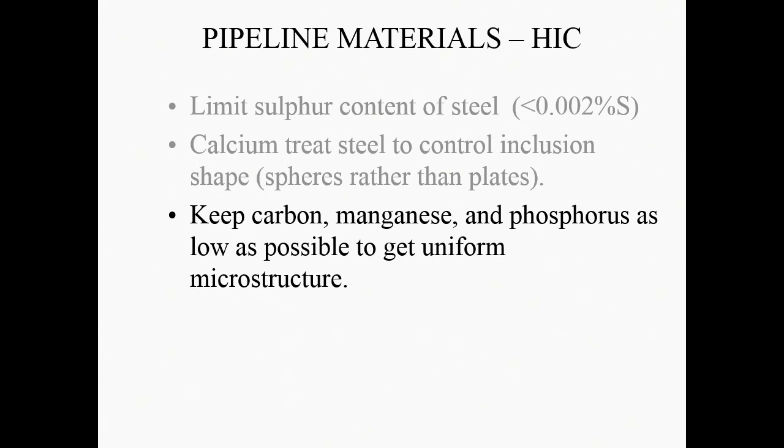It doesn't affect the hardenability, but it's another embrittling element that you want to reduce, like sulfur. Not quite as bad as sulfur, and a small quantity of phosphorus is good because it will increase the strength of the steel, but too much phosphorus and then you can get brittleness, so you want to avoid that. And hydrogen just makes all these things worse. So anything that makes a steel brittle, if it's in the presence of hydrogen, it will make it more brittle and much worse.